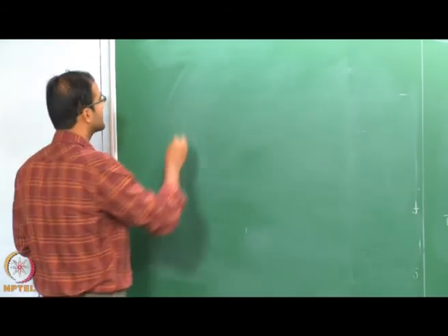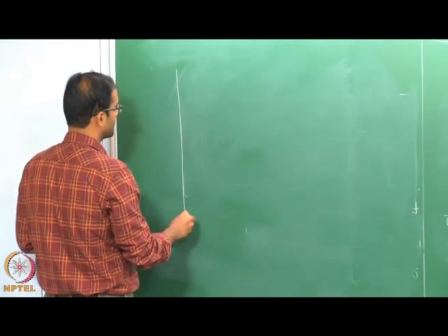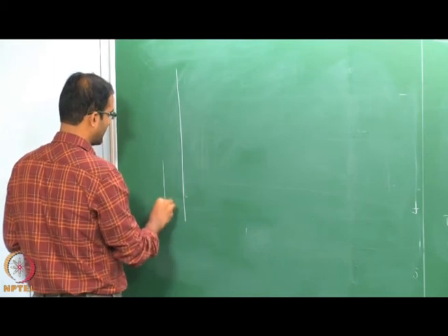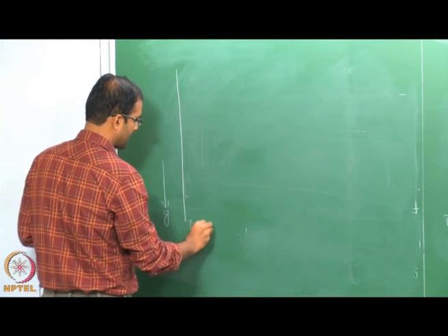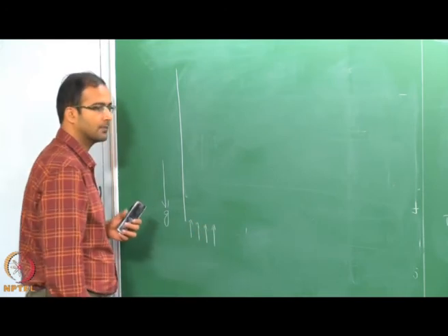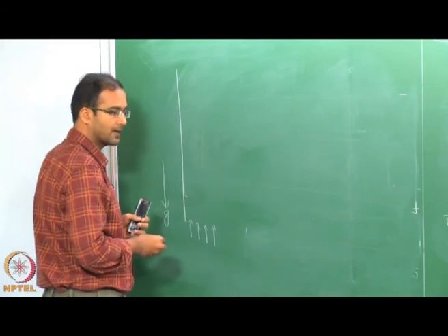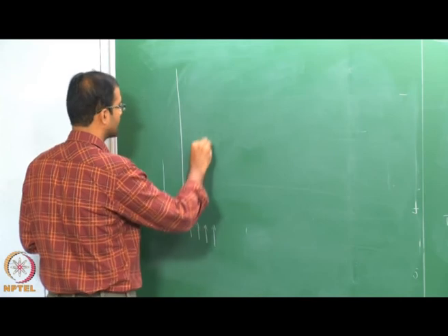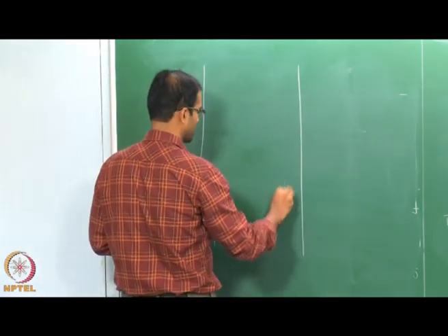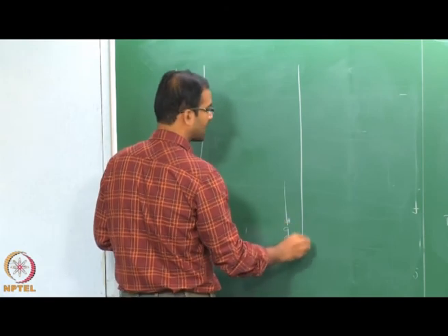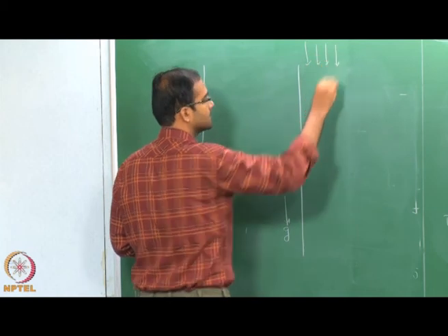So in that case, what happens to the flow patterns? For example, if you talk about gravity acting downward and you have a forced motion, bulk motion of fluid, and along with that a natural convective boundary layer. Okay. So this is one case. The other case is where the buoyancy is acting upward, but the forced motion pushes the fluid downward.